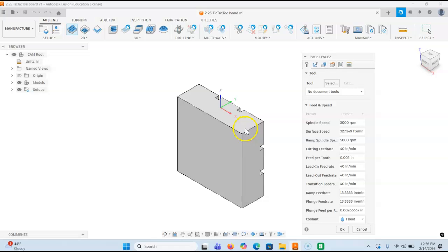Sometimes, and you guys know from experience in the lab, we'll machine in one direction, move over a little bit on the Y, and machine back in the X. So that's another strategy. You could say that's a zigzag in the X and Y. Sometimes people will zigzag across this way. I tend to zigzag along the longest dimensions as opposed to the shorter dimensions as far as tool strategy goes. And when we talk about tool strategies, we can also talk about cutting strategy definitions as well.